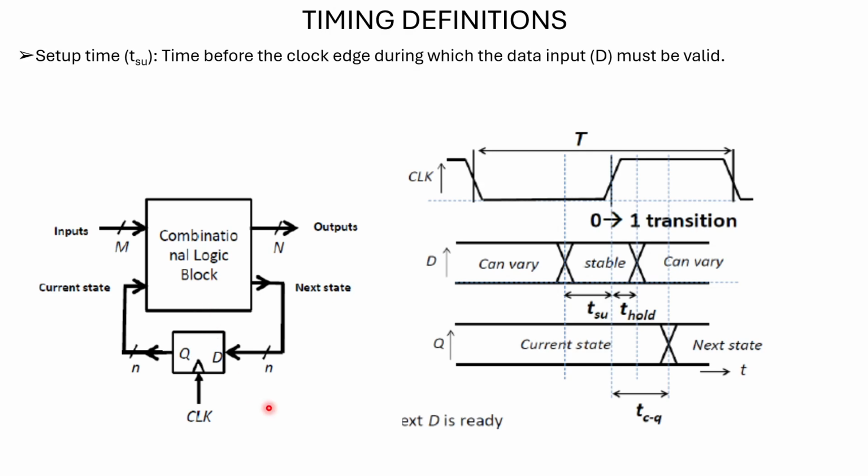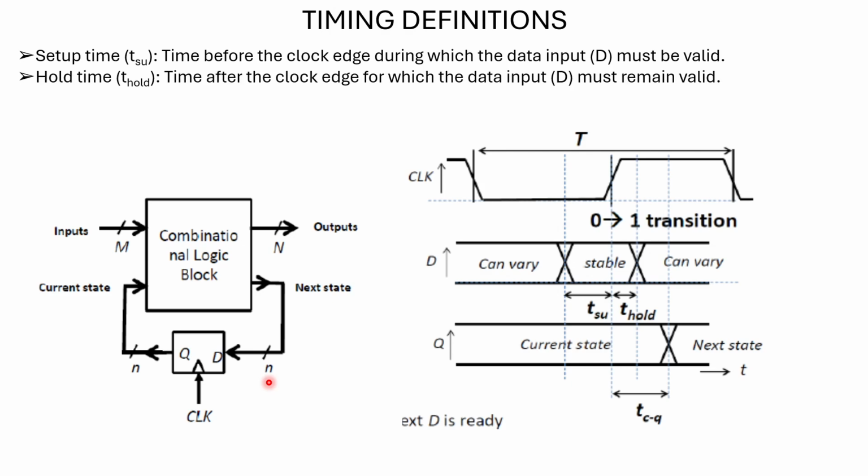So what we have here is a setup time, the time before the clock edge during which the data input must be valid. I won't go into the physics of why we need setup time and hold time. You can refer to our lecture notes or some reference materials, because this is a problem solving session. I have just left that part. And then the hold time, the time after the clock edge for which the data input must remain valid.